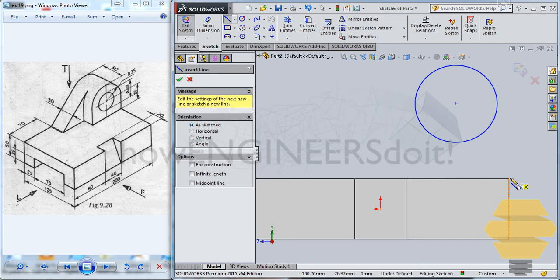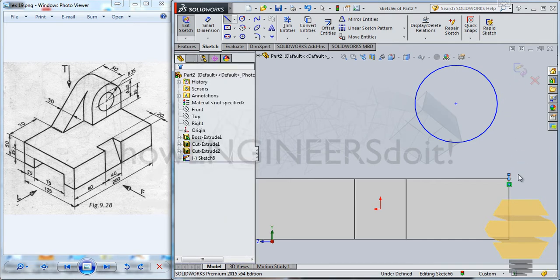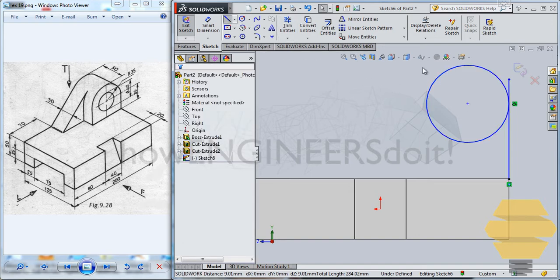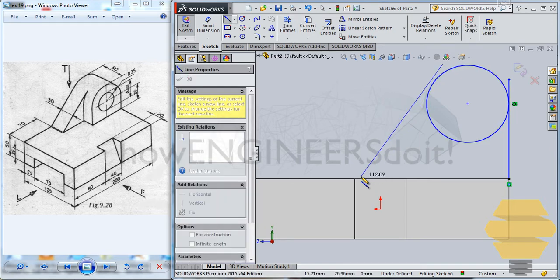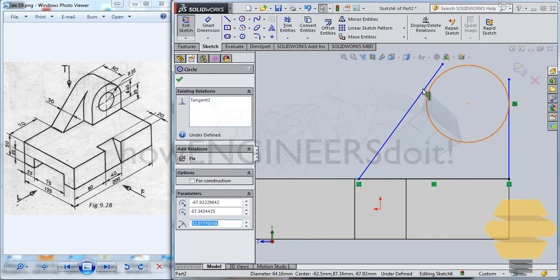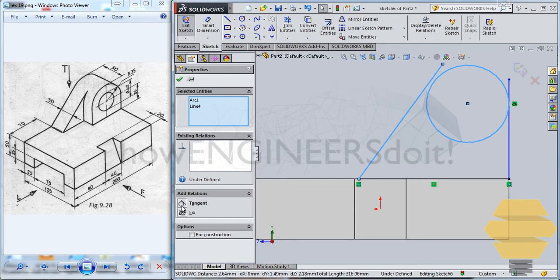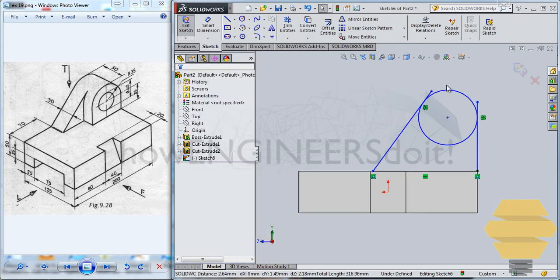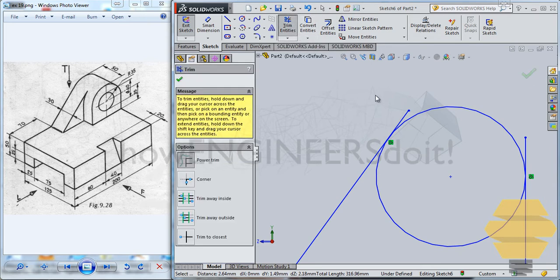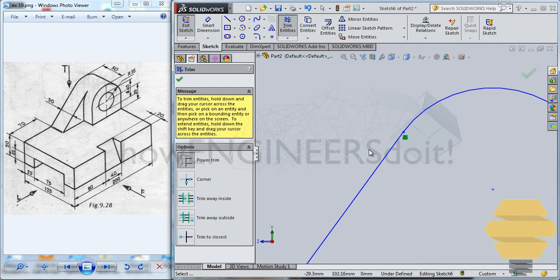and also I'll create a line vertical, and dimension tangent, make it tangent, and also create another line and just also tangent this and this here, tangency. Now you can simply zoom in a little bit and use the trim entities, power trim this portion as well,